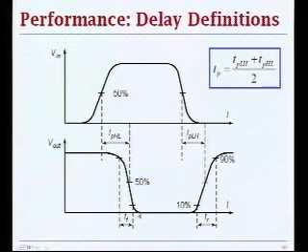And this is again a definition issue: you can define HL relative to the input or to the output. In this case, you can say this is maybe TPLH because input is rising, but we always refer to the output case because sometimes you may have inverting gates, sometimes you have non-inverting, and so on. So we define our delay numbers relative to the output.